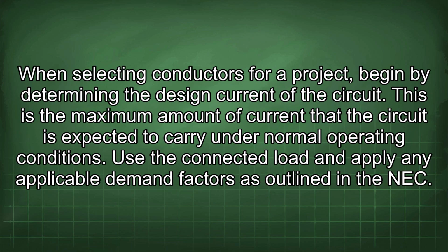When selecting conductors for a project, begin by determining the design current of the circuit. This is the maximum amount of current that the circuit is expected to carry under normal operating conditions.